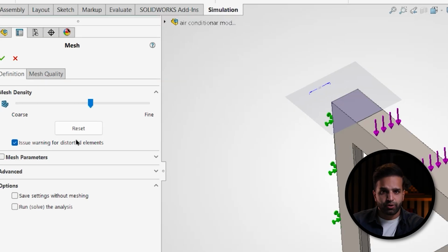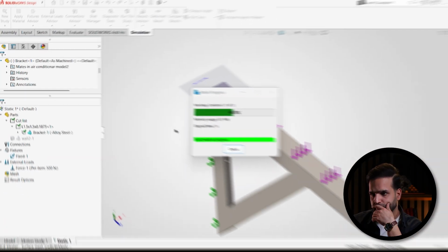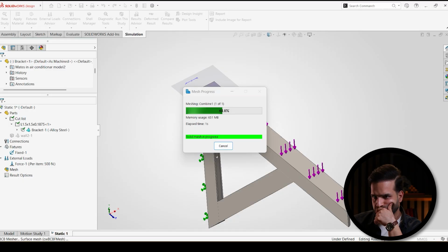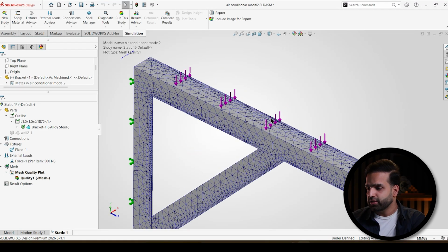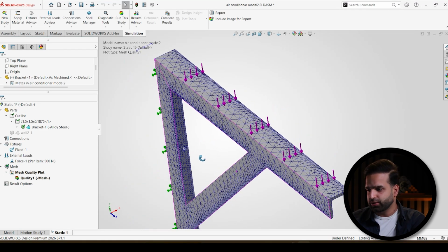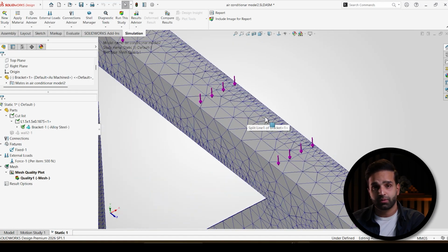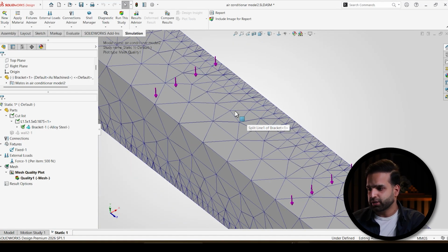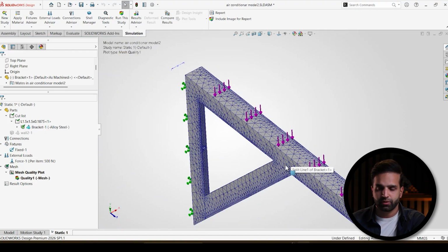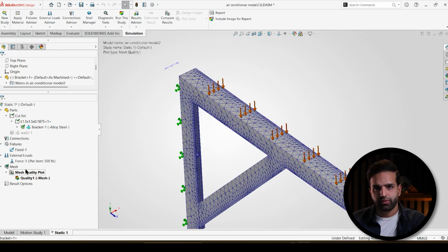In this case, I usually start with a standard mesh with the default values and then refine it where necessary. So I'm going to reset the parameters to the default values and then I'm going to confirm it. Just remember that the default values are a good starting point, not the final solution. So let's confirm it. Well, obviously the quality of the mesh is not sufficient for accurate results. The mesh is too coarse at some regions, and so many elements are not well shaped. It is not very good for accurate stress predictions. So we need to refine it.